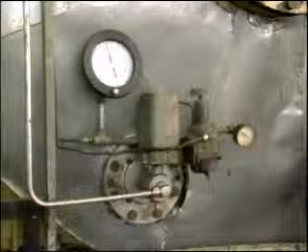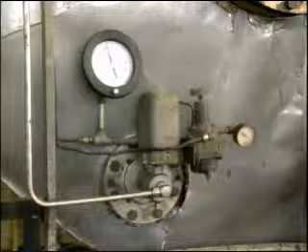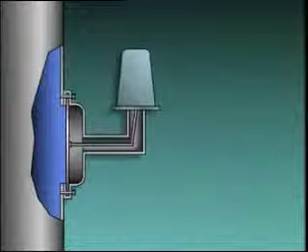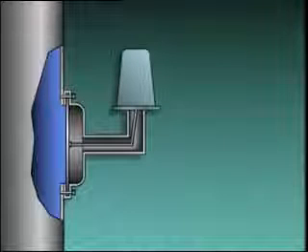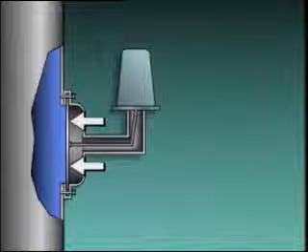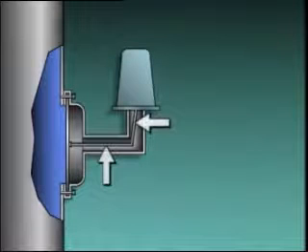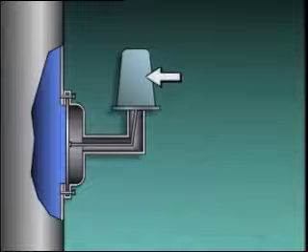That mechanical motion is often transferred directly to a pointer mechanism, which indicates changes in pressure on some type of scale. But sometimes, pressure indications need to be sent to other devices in remote locations, such as a recorder located in a control room. One device that's used for this purpose is a pressure transmitter. Here's a simplified illustration of a pressure transmitter that's installed on the side of a tank containing a liquid. A diaphragm pressure element is mounted onto the tank and connected through a mechanical linkage to the transmitter.